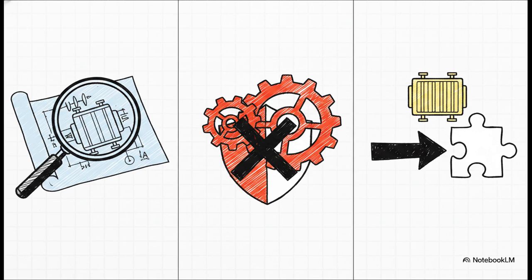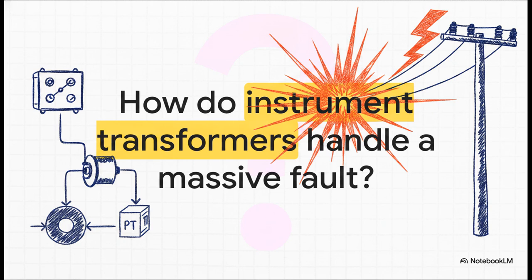Let's wrap this up with the core rules of thumb you need to take away from this explainer. First and foremost, you absolutely must read the network's earthing diagram and verify the CT turns ratios before you specify your relay configuration. Second, differing ratios instantly eliminate the high impedance options, so you can just say goodbye to config C, D, G, and H. And finally, whether your transformer is earthed on the high voltage or low voltage side is going to dictate the final configuration letter you select. The CT ratios dictate the tech, and the earthing dictates the letter. So by matching the relay's configuration to your network's actual earthing and CT setup, you have ensured your invisible fence is drawn perfectly. You are not going to suffer those frustrating commissioning failures.